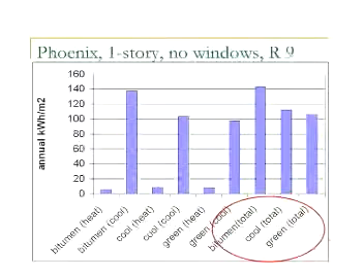So this is the case in Phoenix, Arizona, where again, most of the energy for comfort conditions is for cooling. And you'll see here, looking at the 3 bars on the right-hand side, and these bars are the annual energy use, kilowatt hours per square meter of building floor area. This is the total energy use for a conventional black roof. This is the energy use for a cool roof or a green roof. And you can see that there are some enhancements, a reduction of energy in that case.